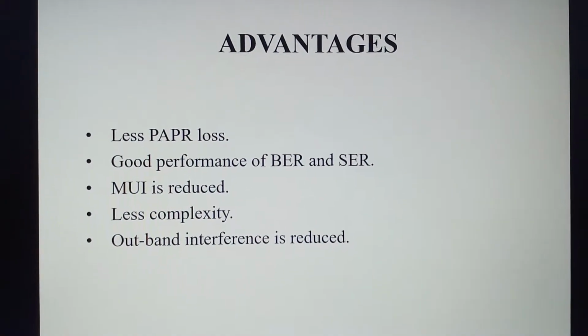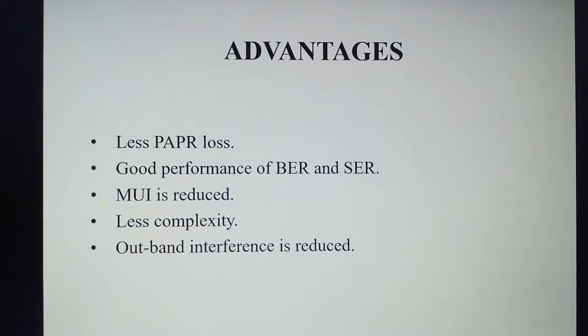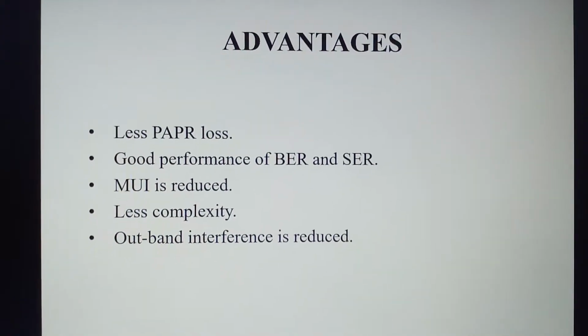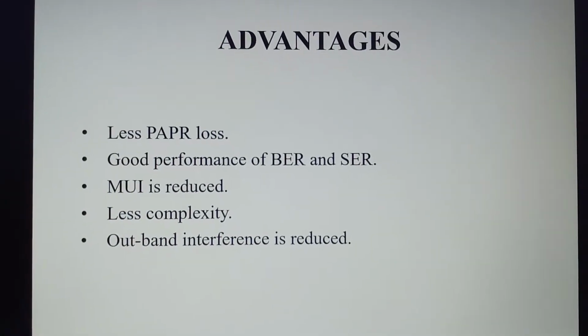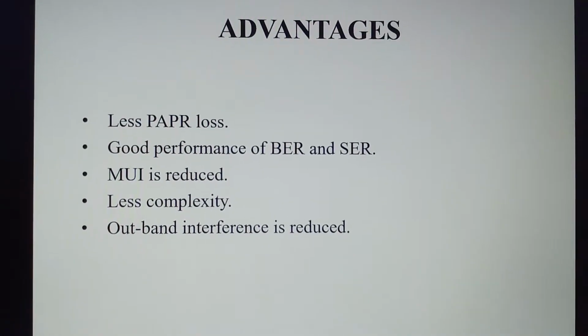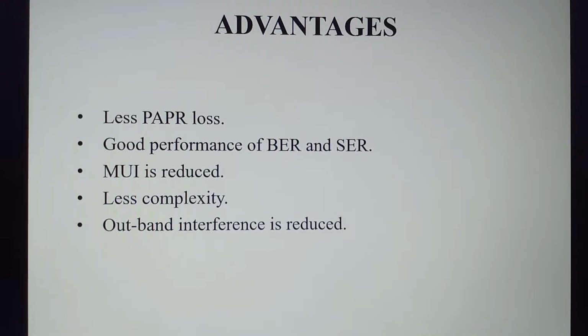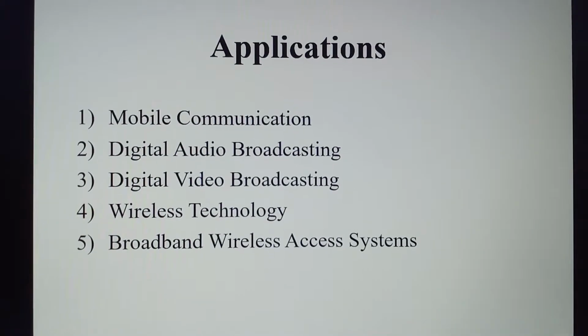Advantages. So we reduce the PAPR up to 6.5 dB, so it means less PAPR loss. Good performance of BER and SNR. Here MUI is reduced and, compared to the previous method, complexity is also reduced. Out-band interference is also reduced.